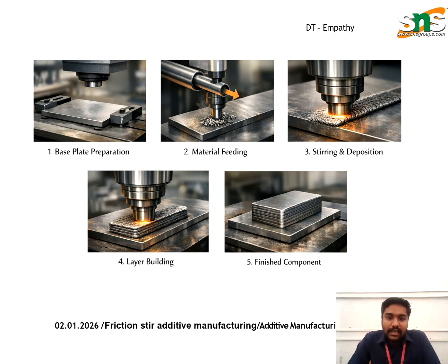After each base plate, the material will be fed at every structure with a layer height of 0.5 mm at every layer. It can vary up to 1 mm. So the layers will be built at 0.5 mm from one layer to another. So it will be easy to overcome the post processing and removal structure.